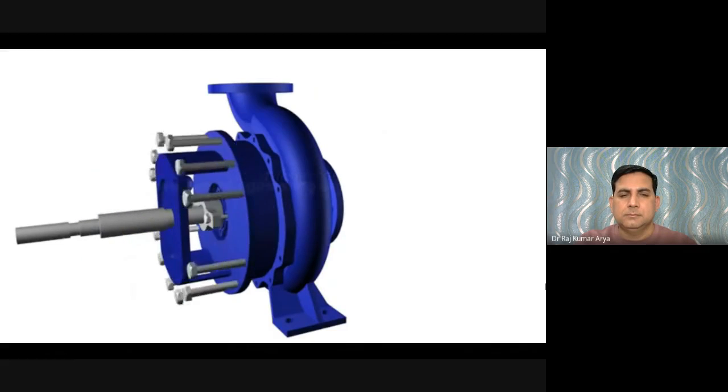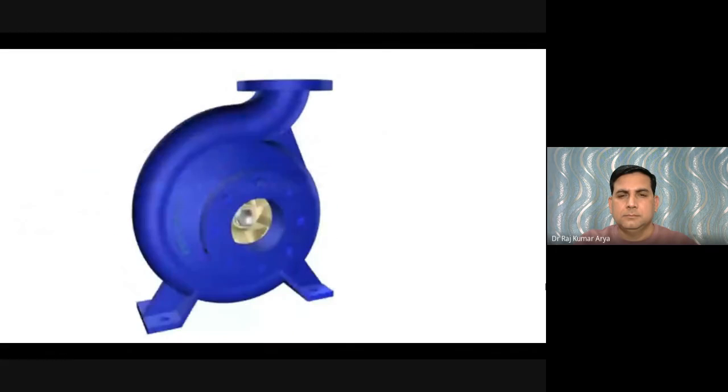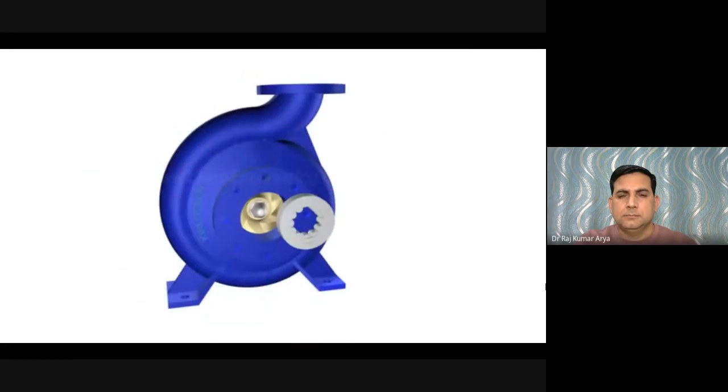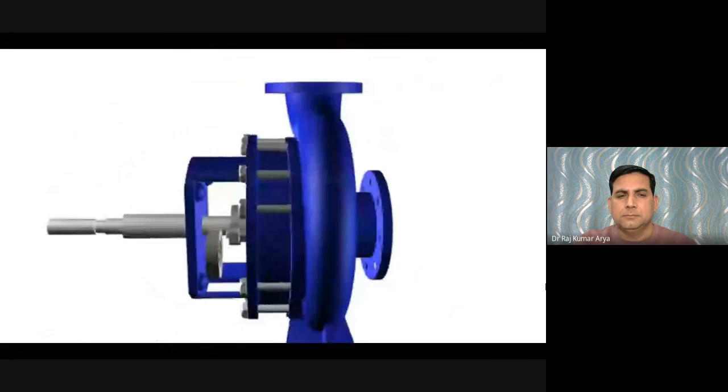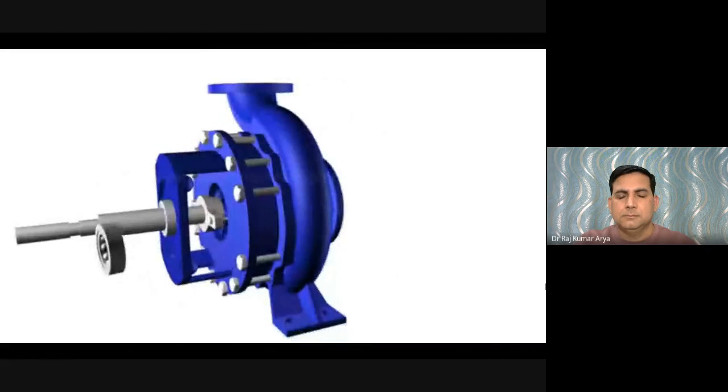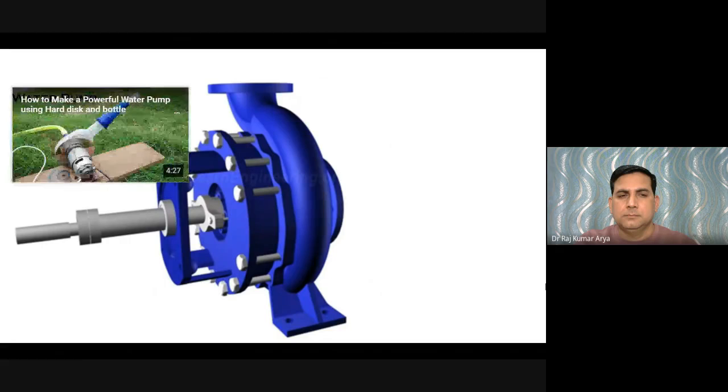Impeller is mounted on bearings, but at the suction side of the impeller, it is not advisable to fit a bearing since it will block the flow. So bearings have to be fitted at the other end. This means the impeller is mounted like a cantilever. For high flow rate pumps, a bearing housing with cooling oil is necessary for improving life of bearings.